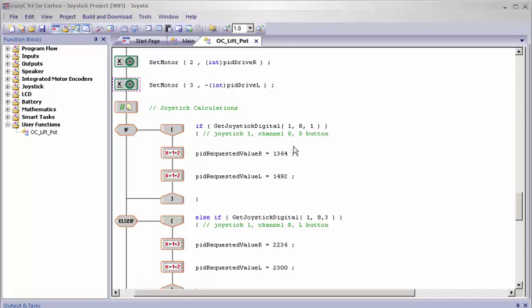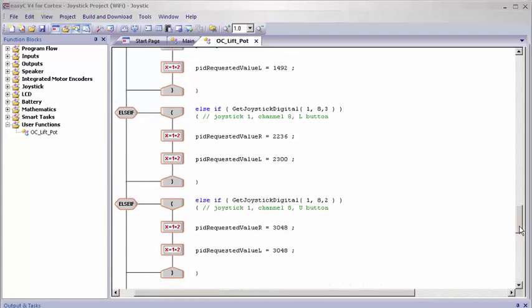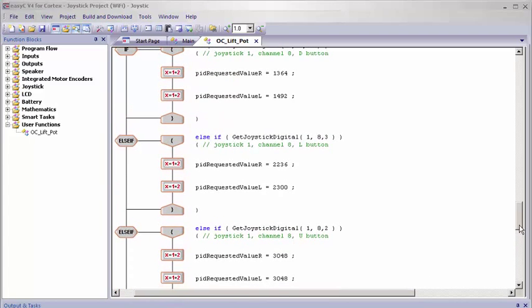Once you have your potentiometers on and they're set, and you have them loosely screwed on to your lift, you need to slowly spin them and calibrate them as you see on the printer screen. You will do that at the maximum height. So you'll do the calibration while it's all the way up, and then record the values as it comes down.